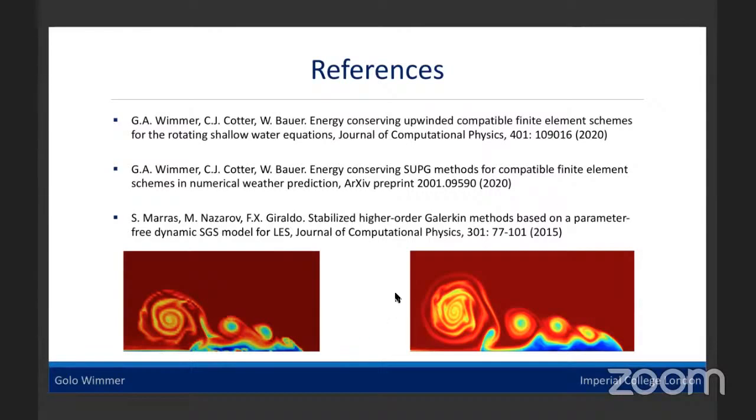I should note that this kind of test case usually comes with an additional diffusion term so that the solution converges to something. And then people usually compare this converged solution. But in this case, they turned off this diffusion term just as we did. We turned off the diffusion term to focus on energy conservation, and they turned off the diffusion term to see what happens with these subgrid features.